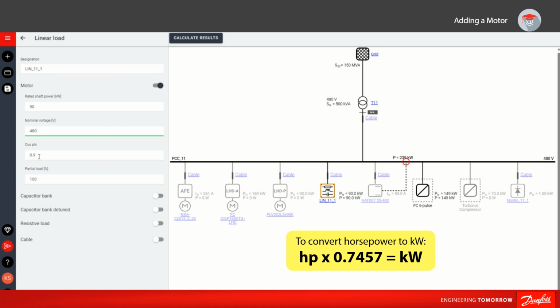If you have information about the power factor and the load of the motor, you can enter this data in the designated fields. The power factor, or cosine phi, represents the ratio of real power to apparent power, and it is usually specified as a value between 0 and 1. The load refers to the percentage of the motor's rated capacity that it is currently operating at. If you do not have this value readily available, it is acceptable to leave the power factor and load at their default settings.